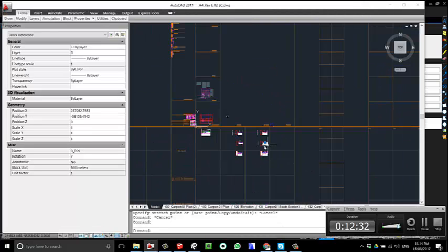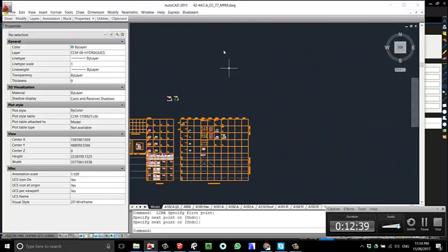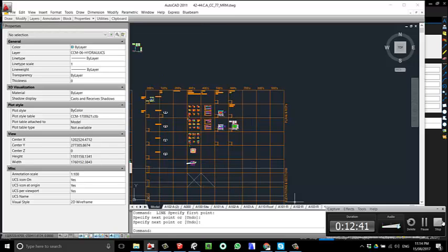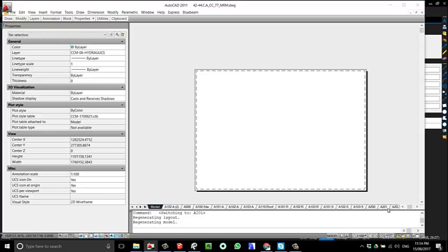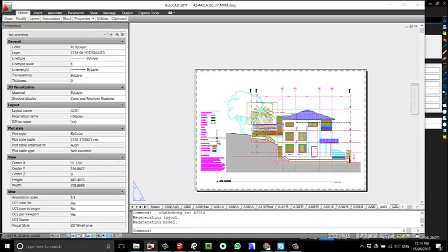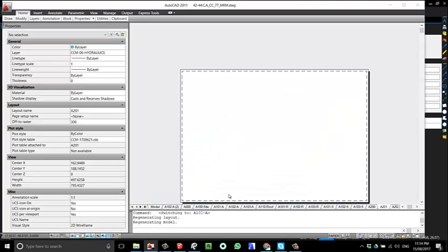So what we need is to, taking from this old drawing, revision E02, all the information we need to this drawing 77, then create with the same naming of plans, the plan 400, 401, 402, and the way you do that is just copy one layout, duplicate the layout, and create the layout as per the PDF shown with the same. Oh, where is the title block? What the hell is the title block?